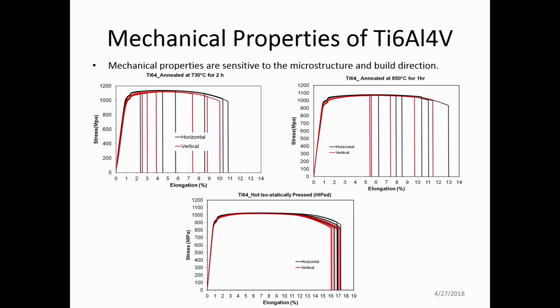And we see a lot of parts coming through with Rolls-Royce now. With electron beam, they're very interested in electron beam, and there's still a lot of variation. They still haven't decided what is the right tensile test bar to use, whereas they might have some very standard tensile test bar shapes for specific materials. With additive, there is no specific one. We are actually testing test bars which are no bigger than 55 millimeters at the moment, which is slightly outside the ASTM scope, which requires you to have a certain width to height ratio.